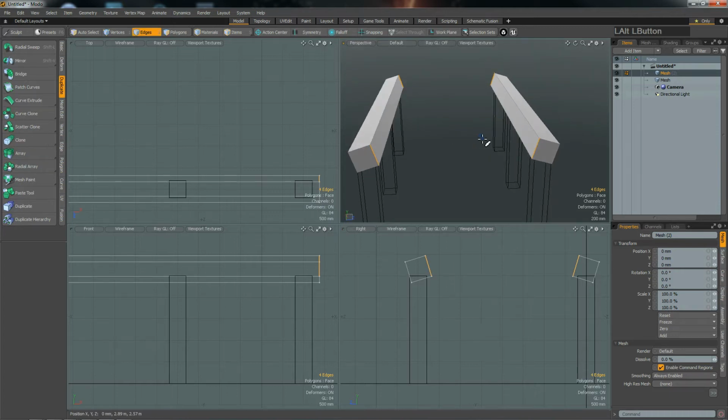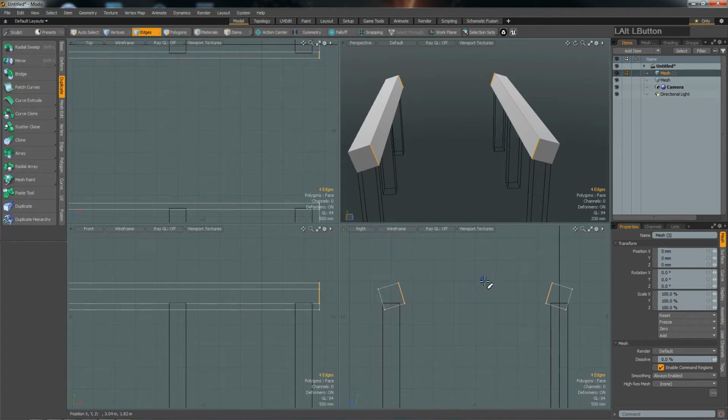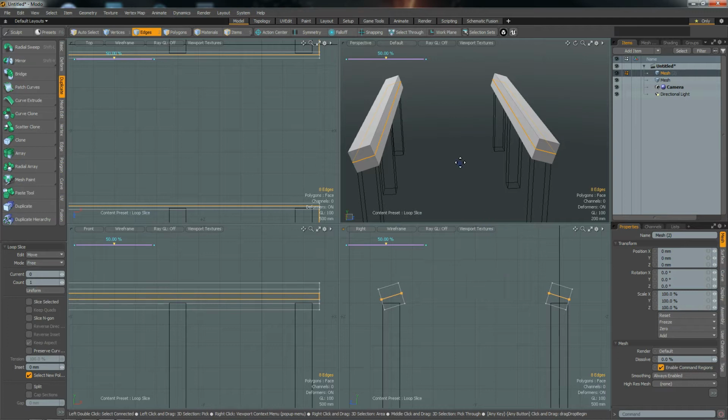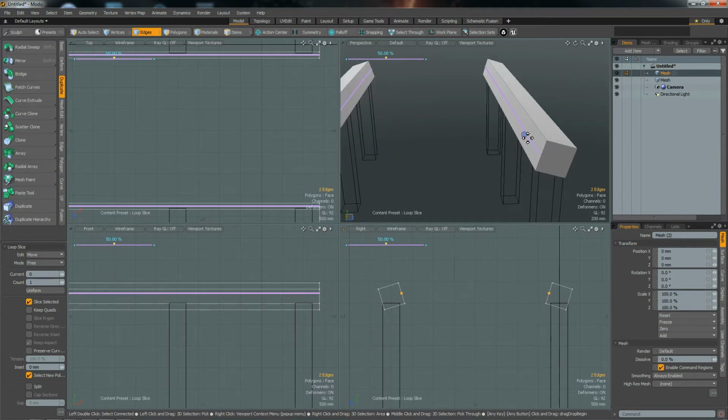But the fewer Boolean operations you do in total, it's generally better for your mesh topology. You don't need to retopologize a lot later on. So now I selected here those edges of the inward side, and I hit Alt-C for cut. Alt-C will just create a cut through my selection. I could also limit it only to my selections, because I don't need the outside cuts here as well.